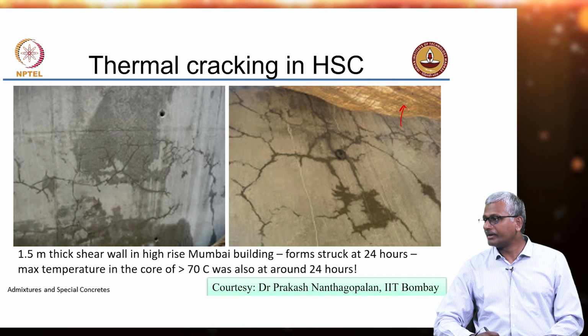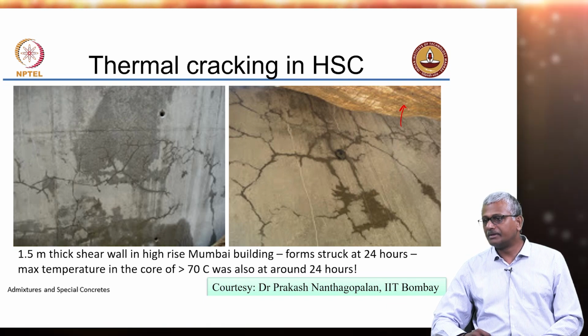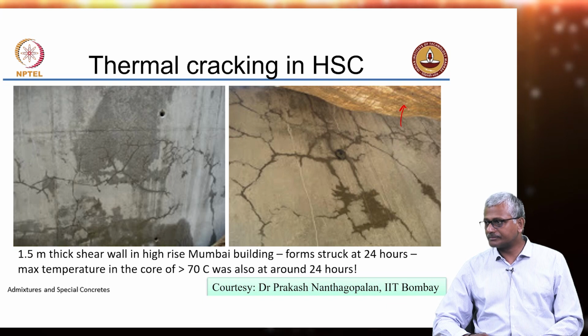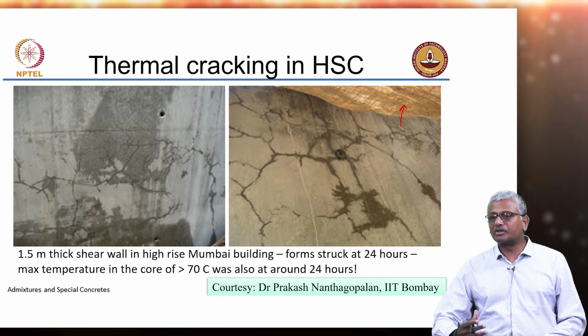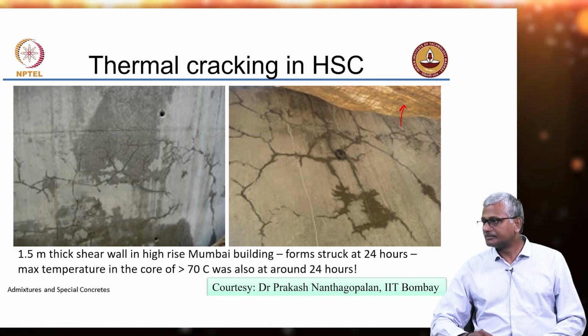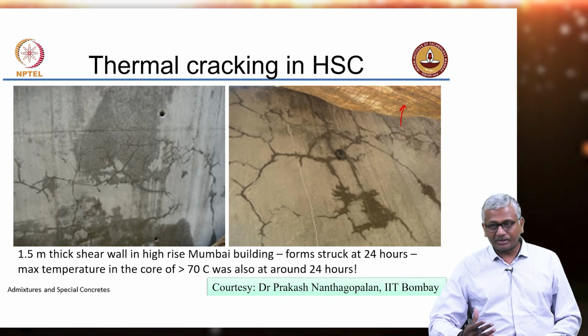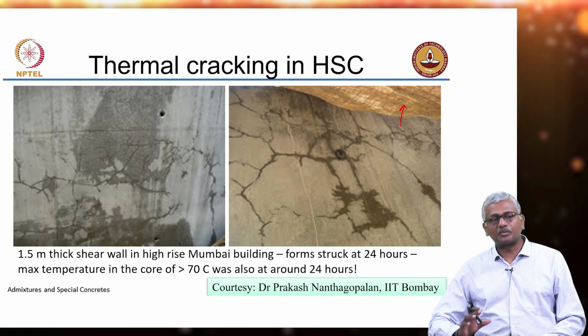Wait longer for? Yeah. So, the formwork can be kept for a longer period of time, right, so that the heat slowly dissipates from the core also. As the structures become larger and larger, this formwork removal becomes trickier, right. So, you have to really plan that. In fact, today I am seeing many projects where this is a major problem.